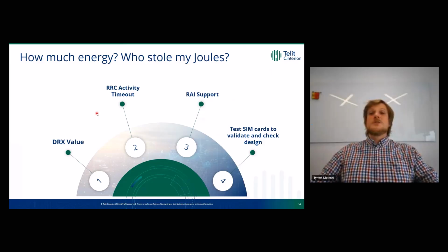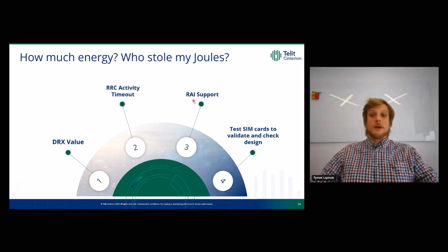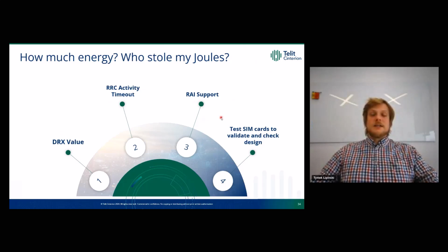So let's summarize. Who is stealing our jewels? First, the eDRX value, so how often the modem listens for paging from the network. Another one is the RRC activity timeout, because if the network configures 5 seconds and does not support the release assistance indicator, we will be in a pickle, a lot of wasted energy for nothing. Ultimately, to validate everything, we have to request test SIM cards from our mobile operator, and validate and check the design in a real network to see how it behaves. We introduce attenuation and noise to simulate worst case scenarios.